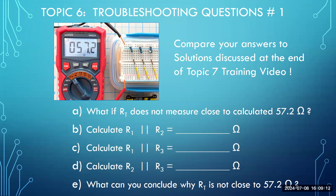The total ohms in a parallel circuit do not add. They do not summate as they would in a series circuit. In a parallel circuit, the value of your total ohms will always, say it again, always, and write that in your journal, always be less than the lowest ohmic branch. So if the first one was 100 ohms, second one was a 220, and the third one was a 330 ohms, your total ohms has to be less than 100 ohms. And in this particular case, we calculated 57.2, and in this case, we measured 57.2.